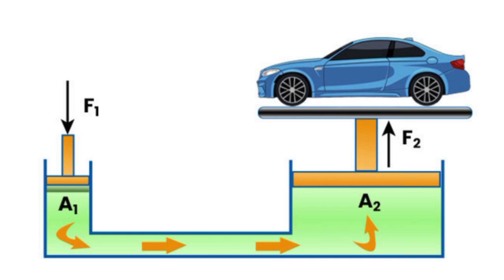Pascal's principle is particularly significant when applied to hydraulic systems. In such systems, two pistons are connected by a fluid-filled pipe. If a force is applied to the smaller piston, the pressure generated is transmitted through the fluid to the larger piston. Since the pressure is constant throughout the fluid, the force experienced by the larger piston is proportional to its surface area. In other words, the greater the surface area of the piston, the greater the force exerted.